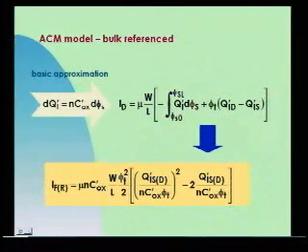But the contribution of ACM is to give a physical basis to the model because, as you could see, the interpolation function was mathematically derived without physical basis. But ACM started everything from an approximation, which is the basic approximation of the model, an approximation of the relationship between inversion charge density and surface potential.